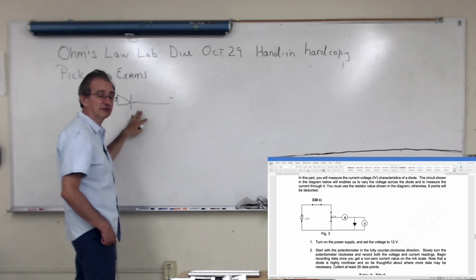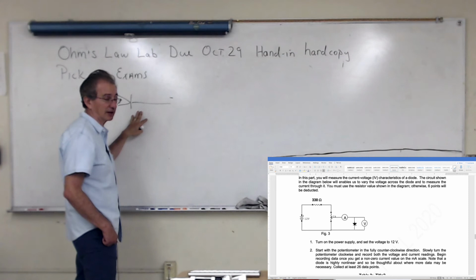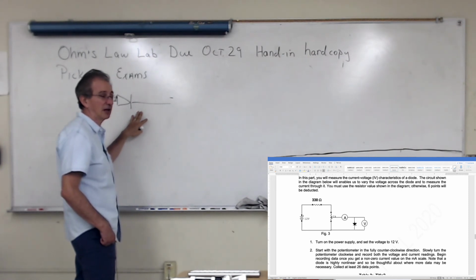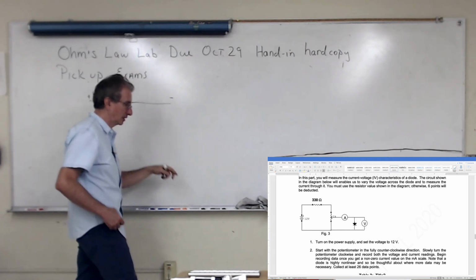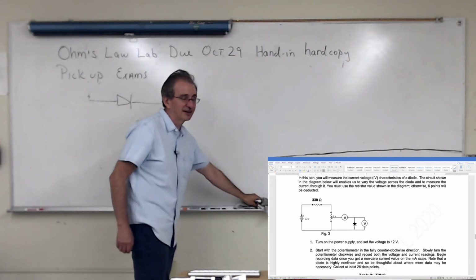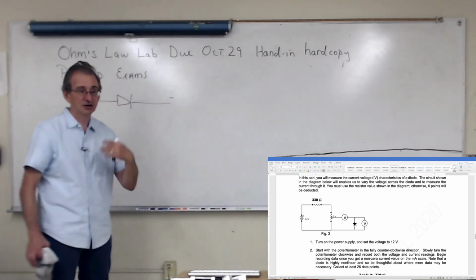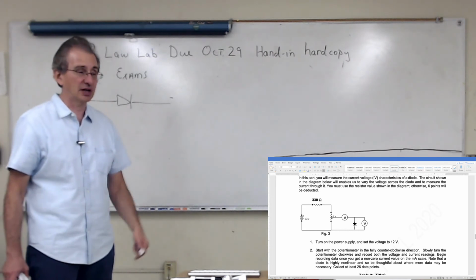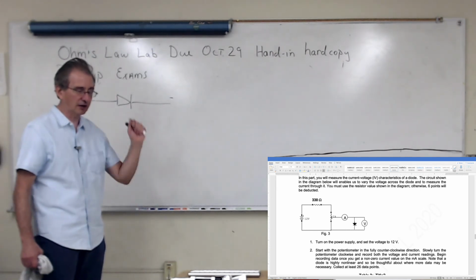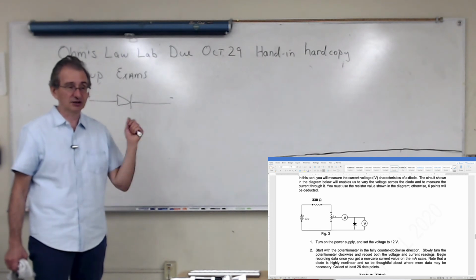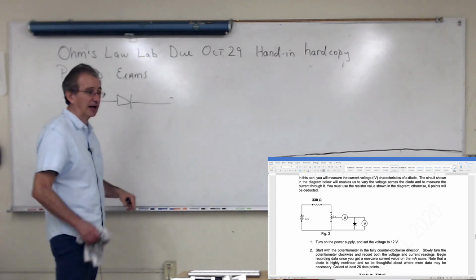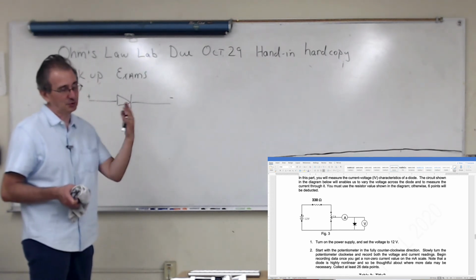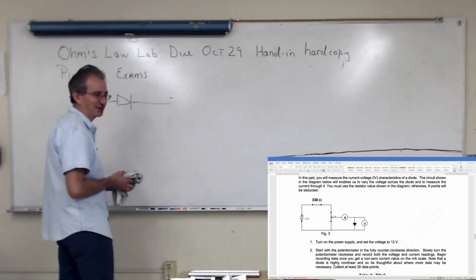The semiconductor device has a lot of applications in real life. You can build a very simple digital logic circuit with this. You can also use a more robust one to protect your devices, a motor, for example, from an inductive load. Like when you turn off a motor real quick, you actually get a large current generated. And you don't want it to go through the motor, you make it go through the diode. Okay, and it'll be kind of an industrial diode for that purpose.